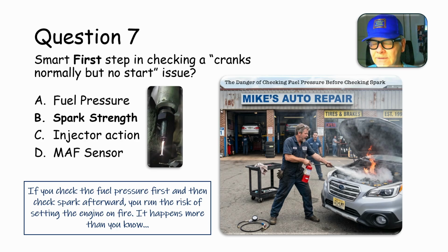I checked the fuel pressure, and there was a little dab of fuel. Sometimes when you're putting the gauge on there, a little bit of fuel will come out of the Schrader valve and dribble around and get on the engine. If you're out on a service lot, you don't have an air blower to blow that out of there. So I was spinning it over with the starter button, and it didn't start, but a spark happened somehow that lit off a little puddle of gas under the distributor. I blew it out, and it came back, and I blew it out, and it came back.